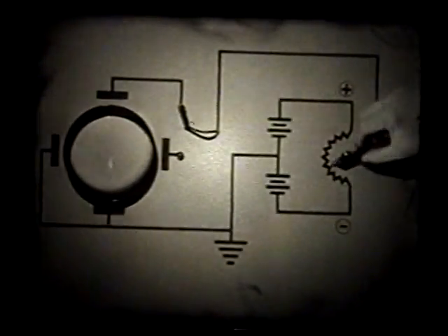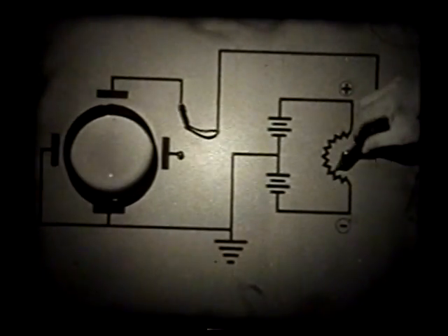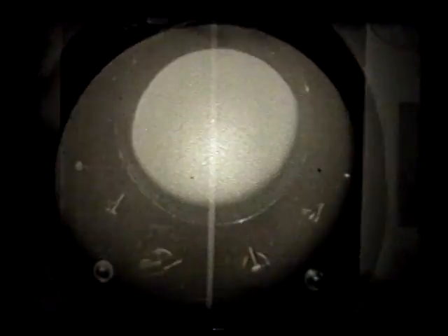Rapid fluctuations in voltage move the spot correspondingly. At high speed, the persistence of the fluorescent screen plus the persistence of vision makes the moving spot appear as a line of light. The apparent extension of the line of light beyond the tube face is because it extends into the shadow of the shading ring.